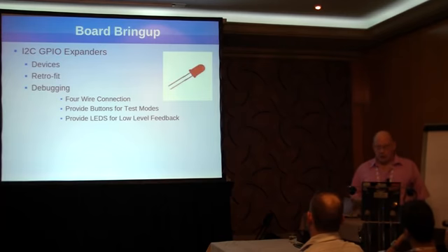Other things that are used are LEDs, of course. I use low-level LEDs for a lot of diagnostics. If you're doing something such as power management development, and you've shut down the UART, shut down all your display interfaces, how do you know you actually reached the level that you're expecting? You can create lots of little different LED configurations that tell you what's actually going on with your power management at the time.